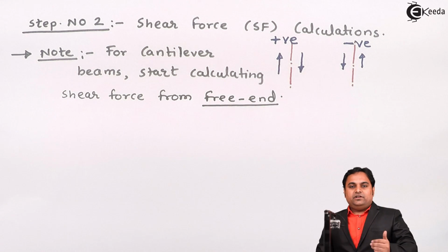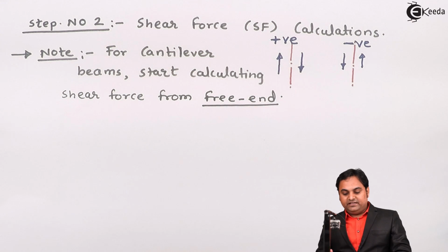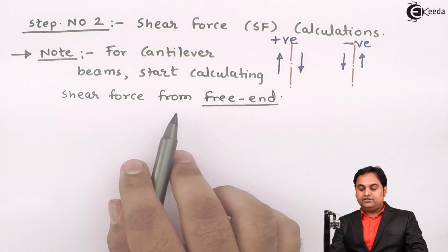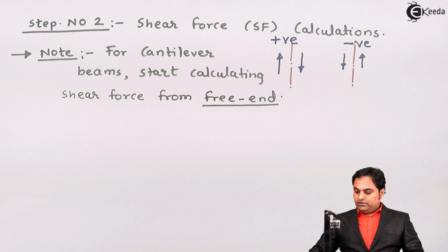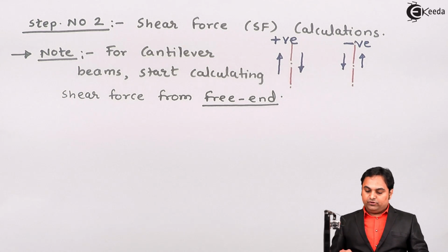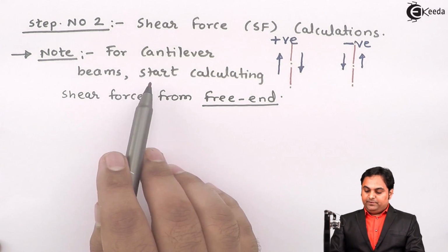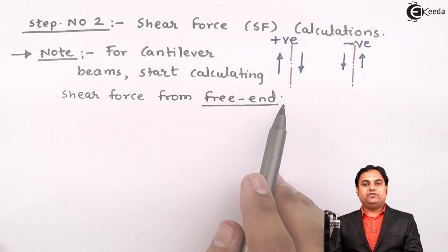So here I have given a small note that for cantilever beams we have to start calculating the shear force from the free end. So now here, as I have mentioned, for cantilever beams, start calculating shear force from free end.